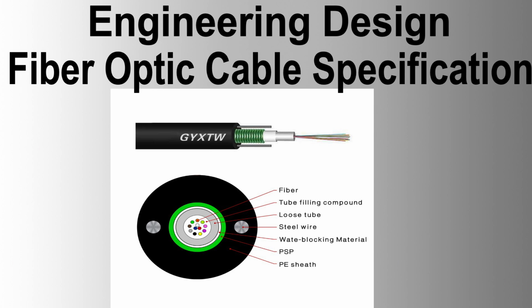Repeated bending. The cable must be subjected to a bending radius of 20 times the diameter of the cable for 6 complete turns, according to IEC 60794-1-E11-E6 test methods. During or after bending, a permanent or temporary average increase in optical attenuation value greater than 0.1 dB at 1550 nanometers shall constitute failure.